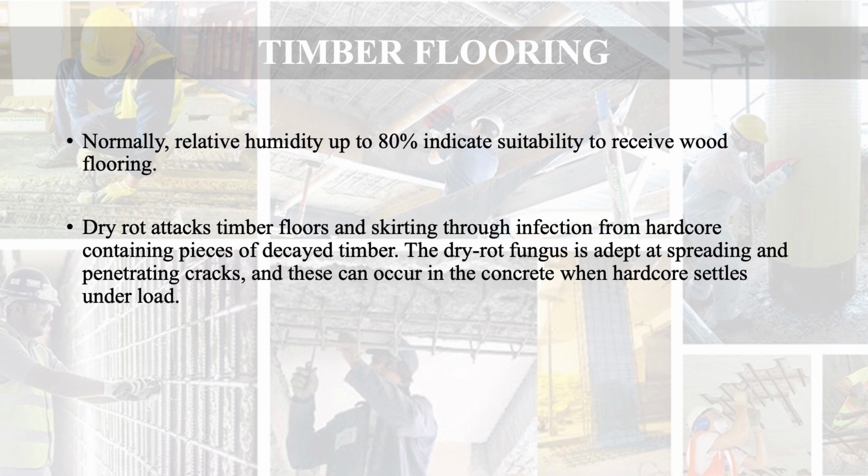Dry rot attacks timber floors and skirting through infection from hardcore containing pieces of decayed timber. It means if there are pieces of decayed timber in the hardcore, then there is a possibility of attack of dry rot. The dry rot fungus is adept at spreading and penetrating cracks, means it moves into the cracks, and this can occur in the concrete when